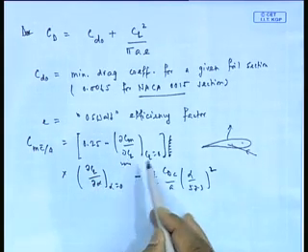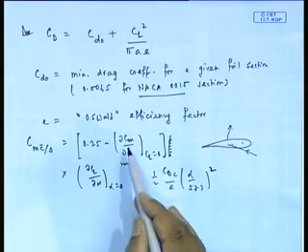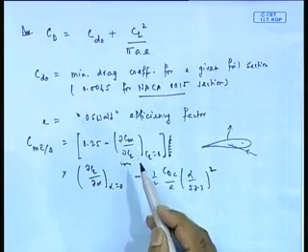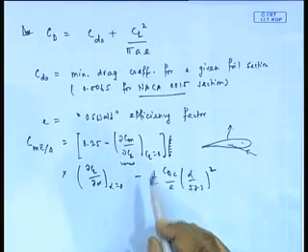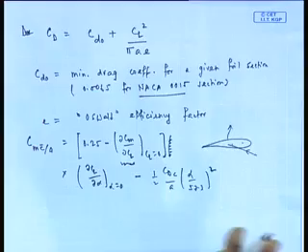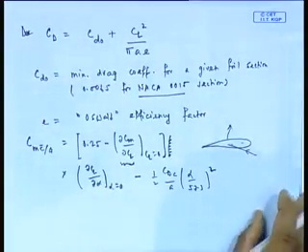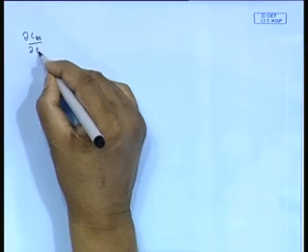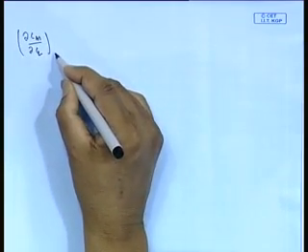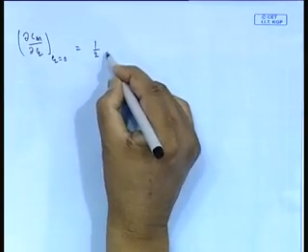This is what is known as the slope of the moment curve against the slope of the lift curve. Basically, slope of the moment curve against lift curve, dCm by dCl. If you studied aerodynamics, you will find out that these are the kind of terms used for aerodynamic lift, wing properties, etc. The formula for that is, since we are writing it, might as well complete this. This formula for that comes to something like that.